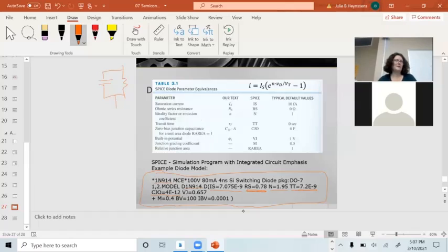Multisim is great because you can go out and pick up a 741 op amp and put it down on your schematic, and it already has the model included for it. If you are using one of the newer, more exotic op amps, Multisim may not have that device in their library, but there are people like Ultra Librarian that will create Multisim models for you, and you can download them. You can download the software for free and actually download the models through DigiKey, through people who are selling you the parts. So they want to help you succeed.